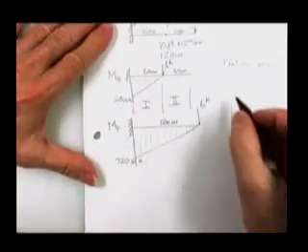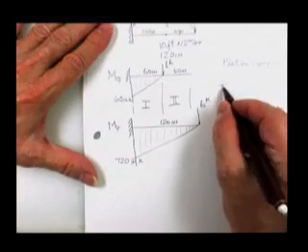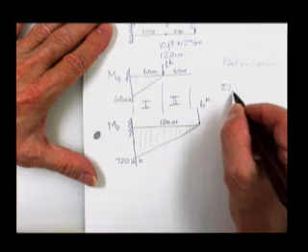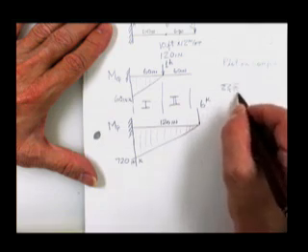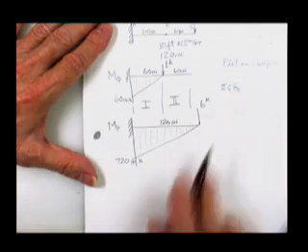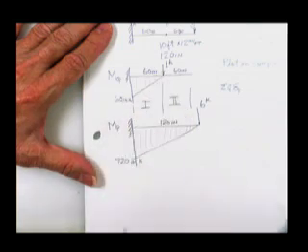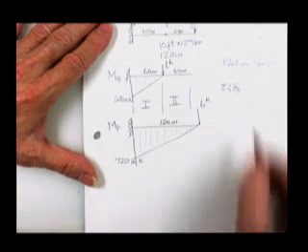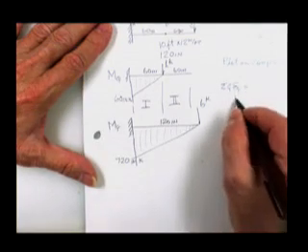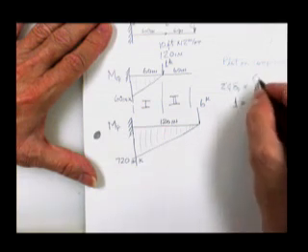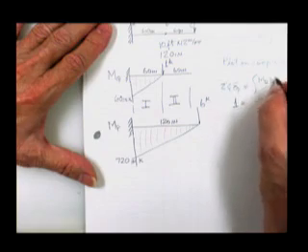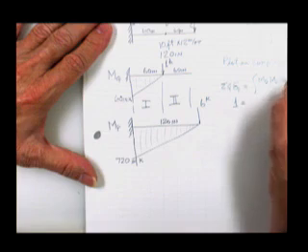So it's my job to say that the sum of all of the Q loads, which will be 1 multiplied times the deflection due to the real loads at the point of application of the unit load in the direction that you decided to put the unit load, is equal to the integral of m sub q m sub p dx over EI.